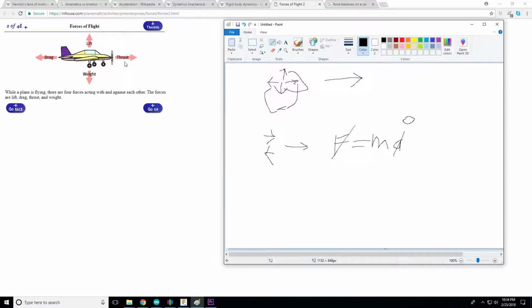So what you have in a plane is when you're flying in cruise, they call it cruise speed, your drag and your thrust are equal to each other. You're not speeding up, you're not slowing down, you're flying at a constant speed. So if you're developing a model aircraft or a full-size aircraft and you want it to cruise at 300 miles an hour, and you've already looked at the drag at that particular speed, you better be able to get a motor and a prop that will be able to develop at least the same force at that speed.